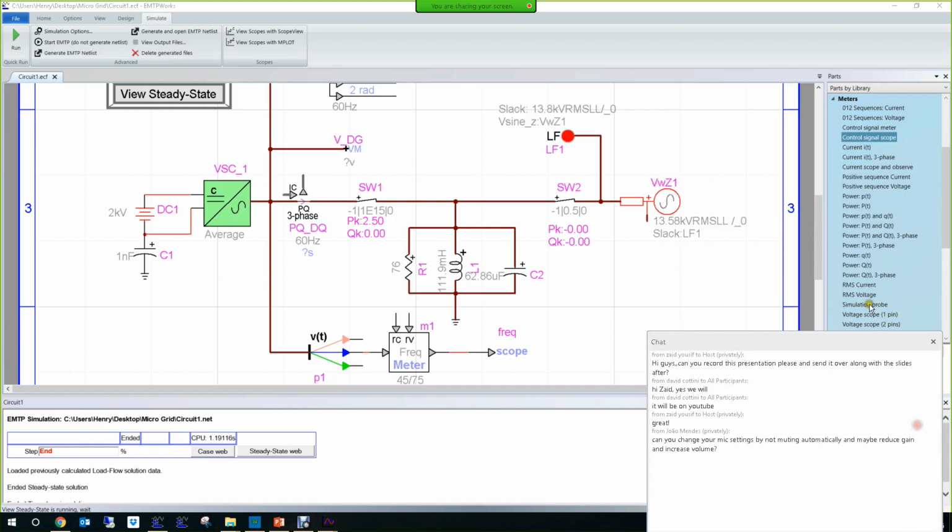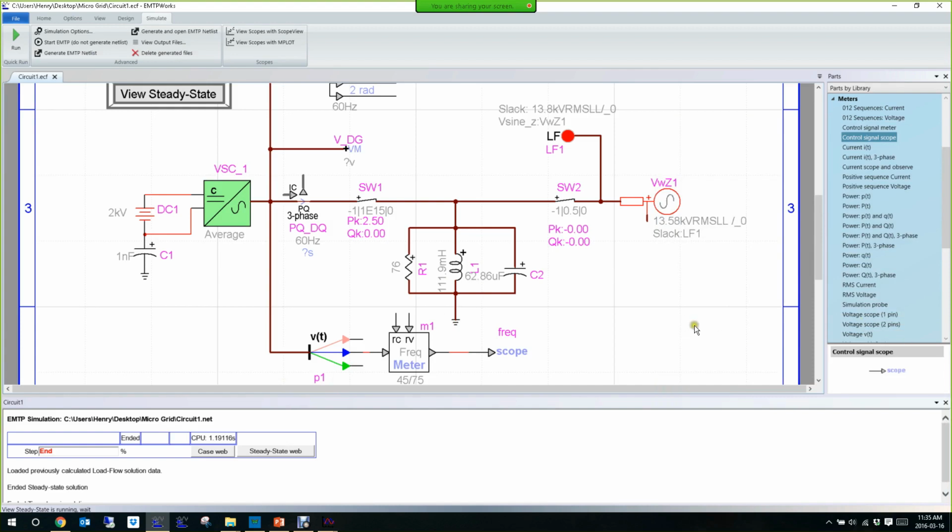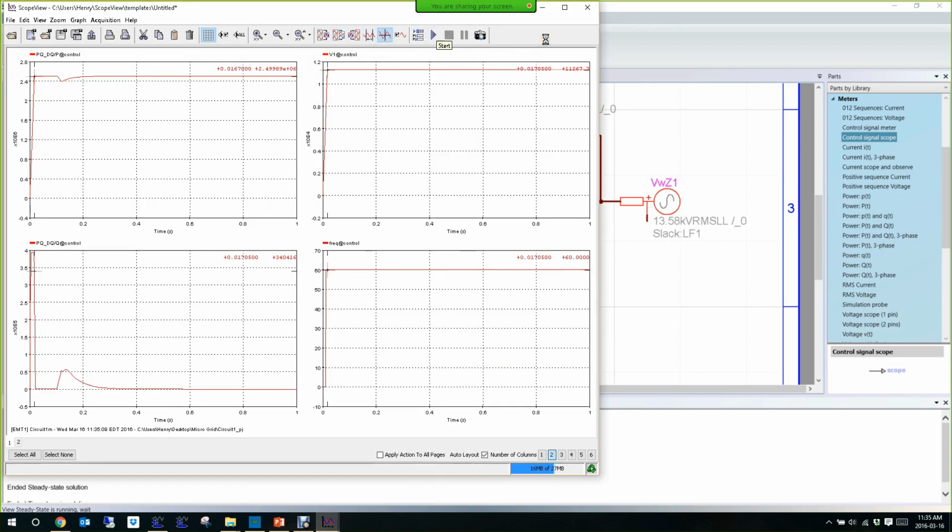It's just that nothing will happen, because here we are in the worst condition possible. No power is from the grid, and the natural frequency of the RLC load is 60 Hz. So we expect nothing to happen. So let's verify. See, it's true. Nothing moves actually. We barely see a difference.